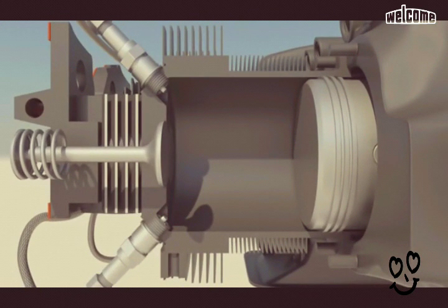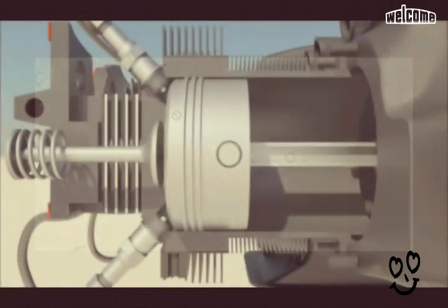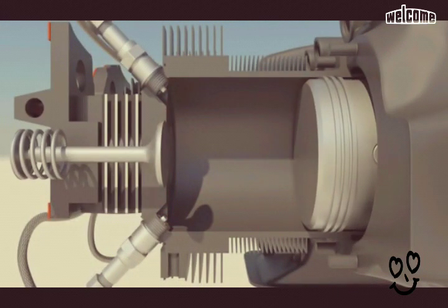However, there are a few abnormal conditions that can affect the performance of the engine. The first one is called detonation. Detonation is the uncontrolled explosive ignition of the fuel-air mixture inside of the cylinders. It results in high temperatures and pressures, which can cause cylinder damage.